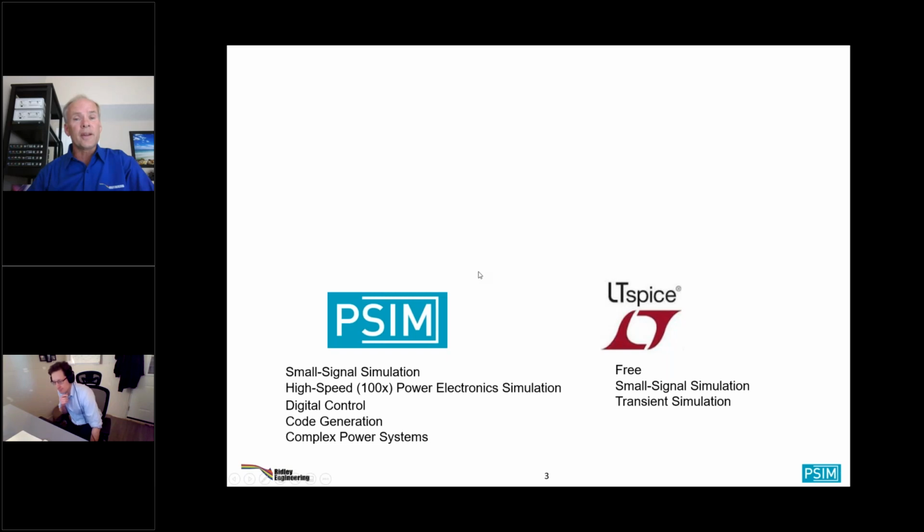And if you want to do really complex power systems, if you've got multiple parallel converters, you'll find LTspice can bog down pretty quickly. So that's where the strength of PSIM comes along. Now, PSIM, LTspice, how do they talk to each other?